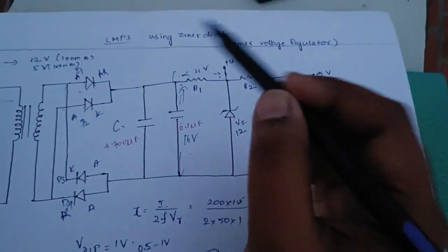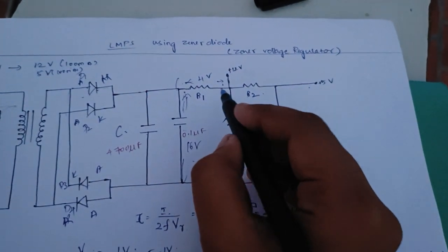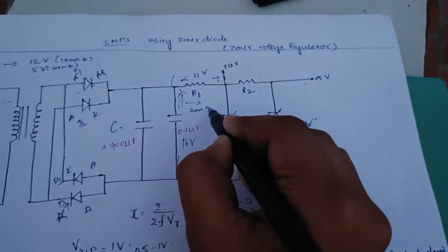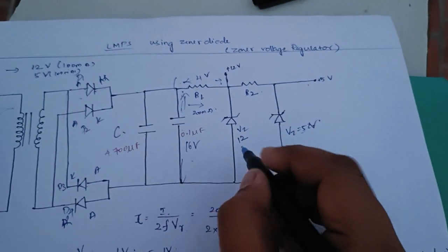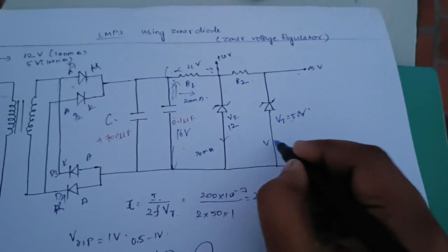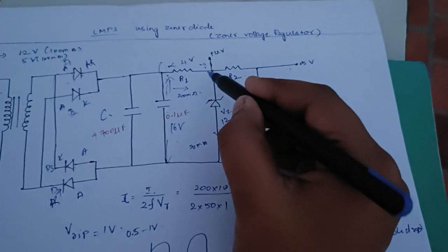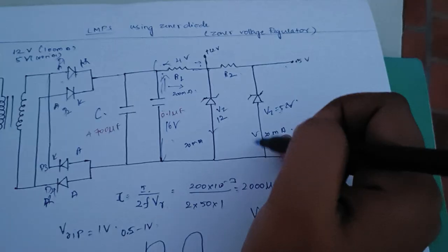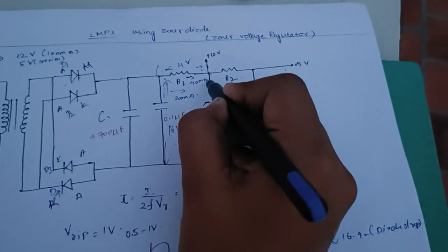Okay, and also what is our max total current here? 200 milliamps. It starts flowing from here. So when this 200 milliamps flows here, we'll keep this. And also the Zener minimum current starting will be 20 milliamps, and here also 20 milliamps. So if the current is splitting from this part only, and this is 20 and this is 20, what will be the current here? Across this it will be 40 milliamps.